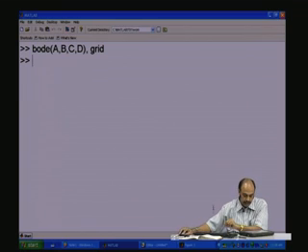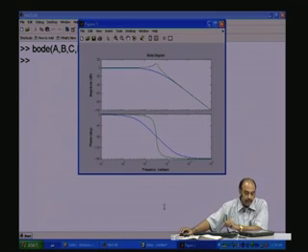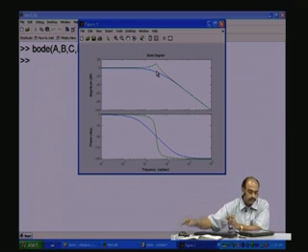Now, look at the figure here, you see something interesting happening. This is the earlier one, the blue waveform, no problems, because the two poles were quite close to the real axis, and once the poles start shifting away from the real axis, it is going to peak. There is a resonant action here, and that is peaking, which is giving an amplification of the gain and then it goes down. And you see the difference also in the filtering action.